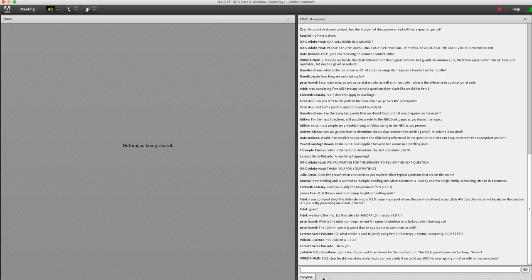The fire and sound resistance tables in volume 2 of the National Building Code are often used, and table 9.10.3.1A gives you a typical sound transmission class based on the assembly you're using for your wall partition. So that answers that question.